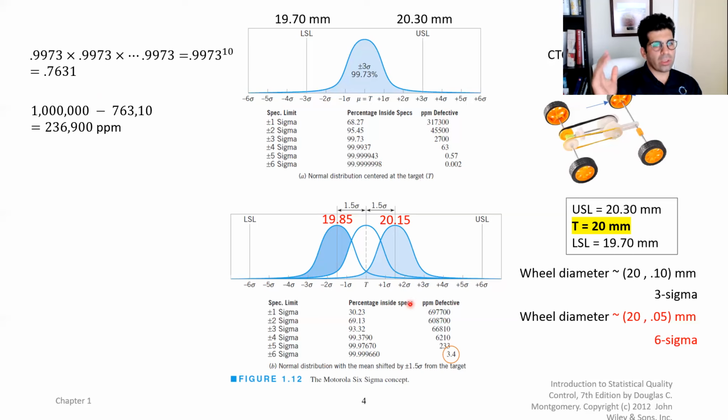And so, in short, to summarize, Six Sigma is the distance between target and USL or LSL. And so the total distance when we're producing in Six Sigma is going to be 12 sigma, from minus 6 sigma all the way to plus 6 sigma, which will be 12 sigma. And also, please remember that this distribution represents our actual production, but these USL and LSL are given to us. Okay. All right. Let's see what's next.